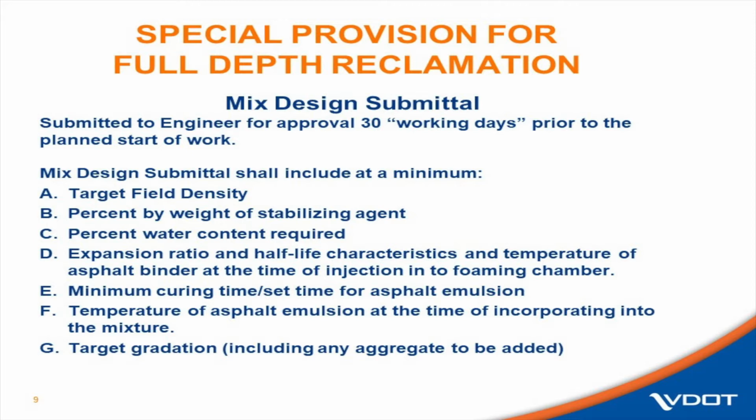Again, we don't do a whole lot of foam asphalt FDR, but that is in there. Minimum cure set time for asphalt emulsion. This is hugely important for emulsion projects because it can take a while to set based on outside temperatures, humidity, weather. Temperature of the asphalt emulsion at the time of incorporating it into the mixture, and target gradation.